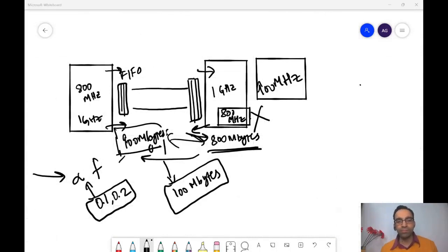Is that okay? So to overcome the latency between these two voltage islands, we use shift registers. Latency means that I'm operating at 1 gigahertz, but to transfer data from one part of the chip to the other, I take 200 picoseconds. So when the clock edge comes on that side, my data is not yet ready there. So I need very small temporary storage, just 1 word or 2 words, and for that I use a shift register. Match up to that speed.